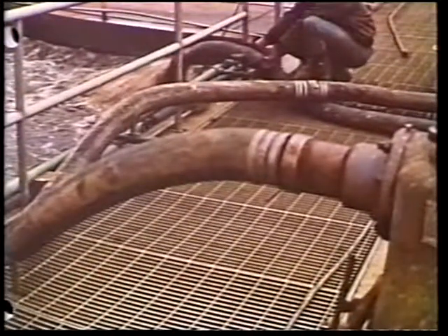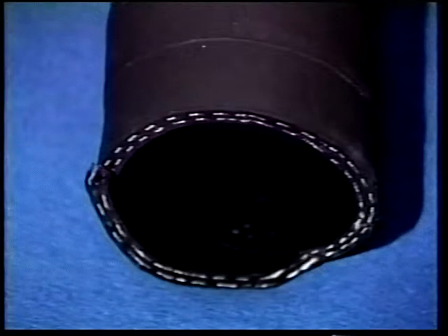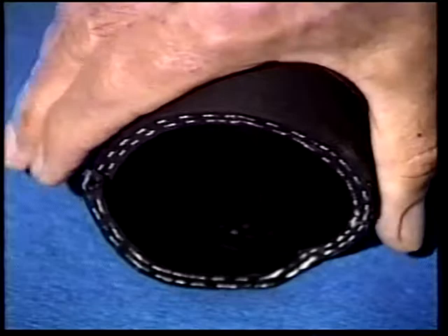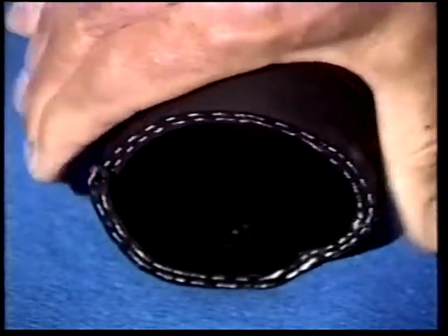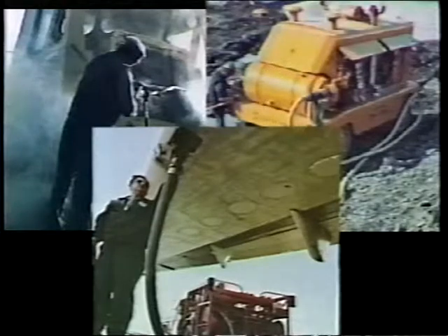Horizontal braid hoses that are to be used for suction applications have an added reinforcing wire spiraled between braids. This results in a hard wall hose with good resistance to collapsing and kinking. Horizontal braid construction is commonly used for steam, heavy-duty air, and petroleum hoses.